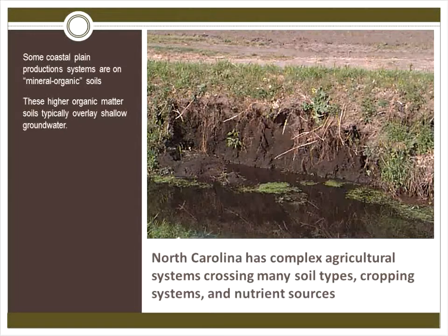In addition to finding sandy soils, you can also find mineral organic soils. These tend to have fairly large amounts of organic materials, and they're typically overlain by shallow groundwater systems, and so it provides the need to drain these soils on a fairly regular basis.